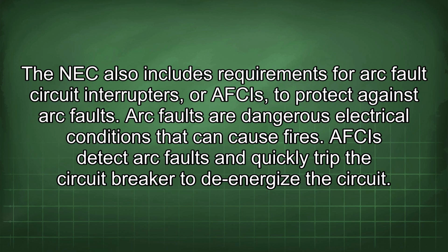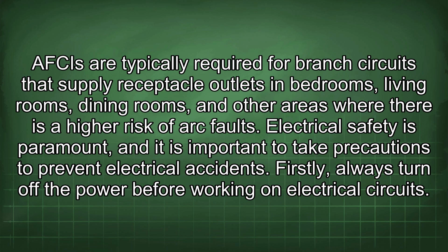Arc faults are dangerous electrical conditions that can cause fires. An AFCI detects arc faults and quickly trips the circuit breaker to de-energize the circuit. AFCIs are typically required for branch circuits that supply receptacle outlets in bedrooms, living rooms, dining rooms, and other areas where there is a higher risk of arc faults.